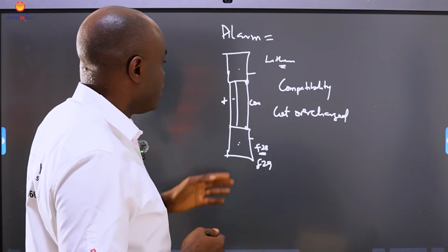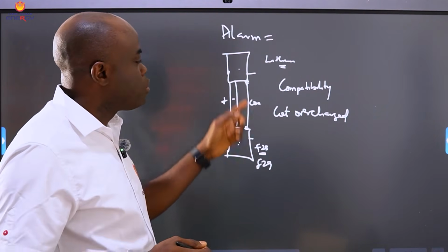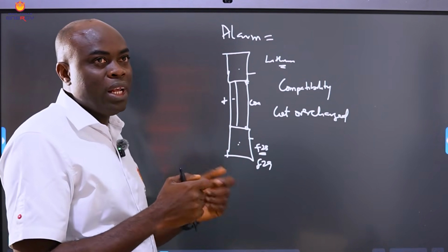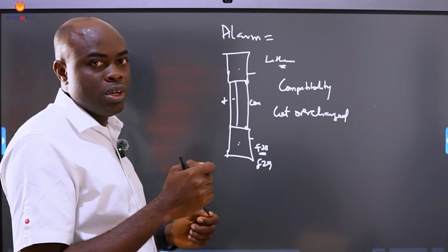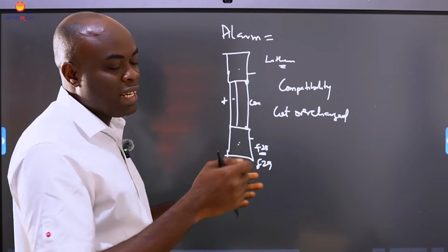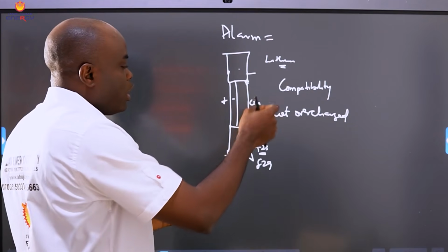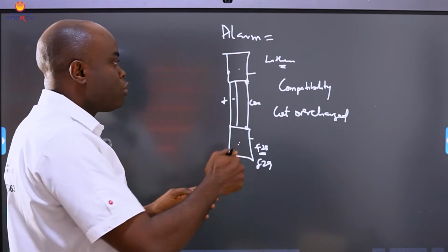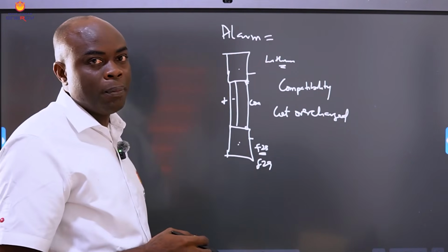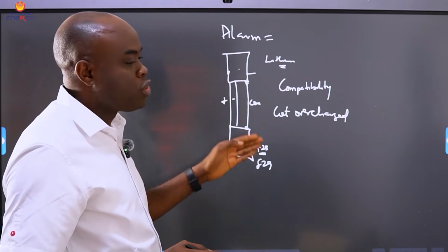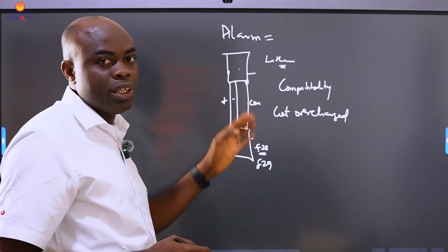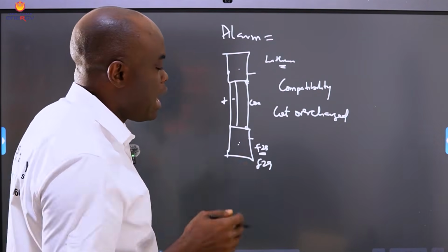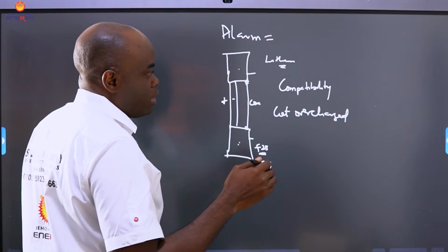So it's very important. Also, if you don't have these cables connected, or maybe the cables were connected before and something probably happened, it's pulled out. Sometimes maybe if it's an exposed place, someone might just go pull it out, or in the process of trying to do maintenance, it's pulled out. When it's pulled out, your inverter will give you an alarm that you have selected lithium, but there's no communication in between. So you have to trace it also. There was a time I had a site.